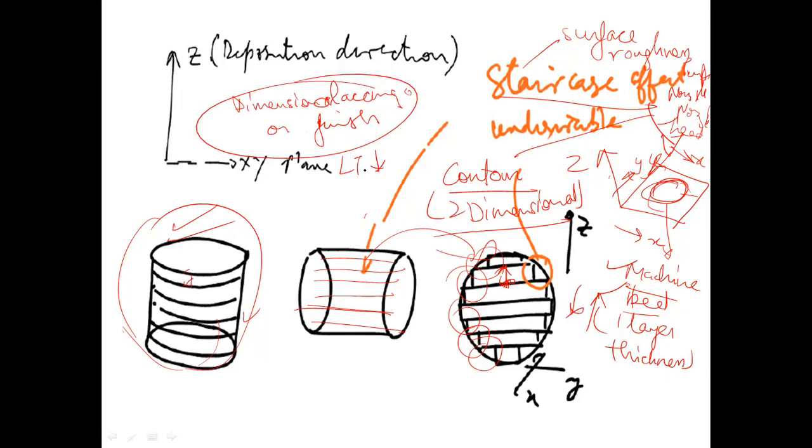And the orientation, now let me come back to orientation. The orientation has to be such that the contact area with the machine bed has to be minimum. Because what happens is the bottommost layer that is in contact with the table generally gets deformed out. As a result, what you will observe is something of a deformity.